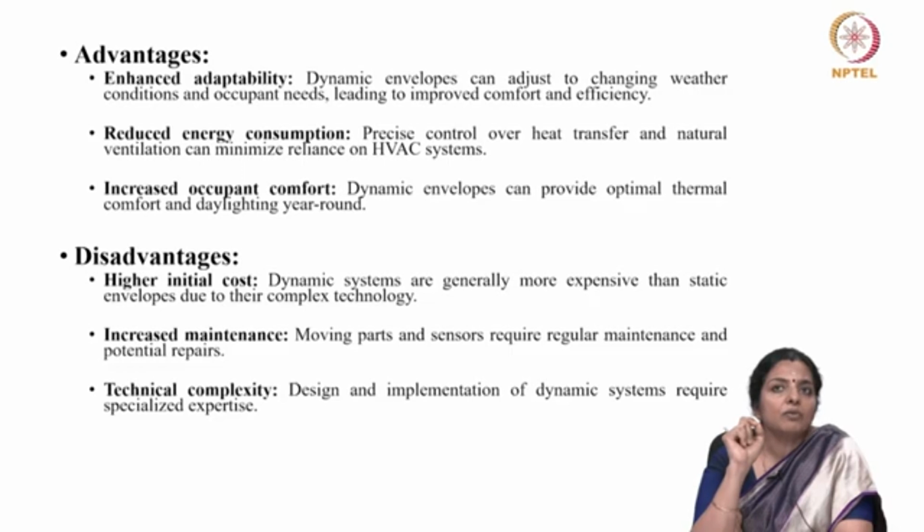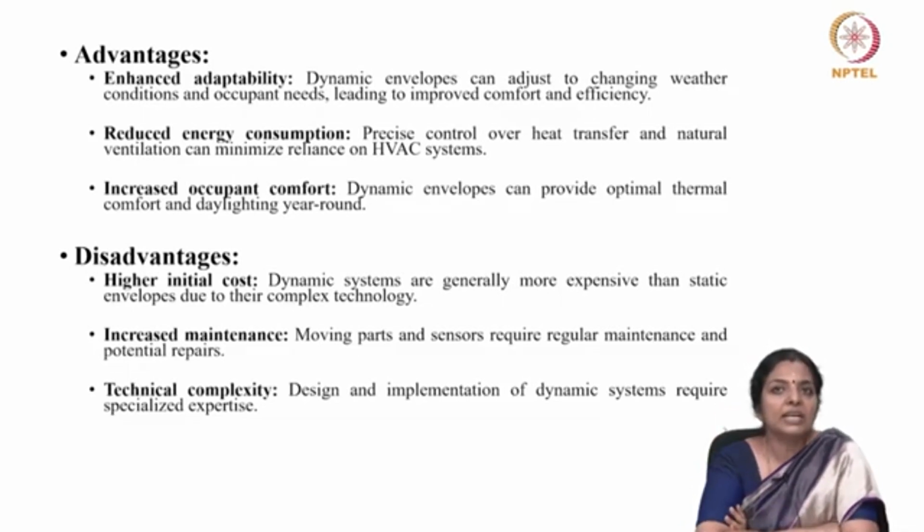The energy performance of different envelope components such as walls, roofs, floors, ceiling, windows, affects the energy required for the building's heating and cooling, and indoor comfort, ventilation and natural lighting. The design variables such as geometry, glass reflectance, the thermal mass, the shading devices, etc. also affect the energy performance.